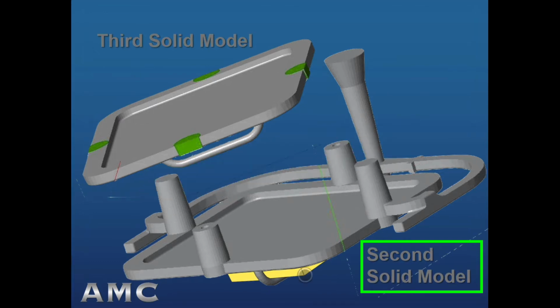And then finally, all of the process interface geometry to fill the mold cavity, to vent gases from the mold cavity as the metal flows in, and reservoirs of liquid metal strategically located to feed solidification shrinkage to set up the mass and temperature gradients to achieve the solidification integrity required for the specified mechanical properties.